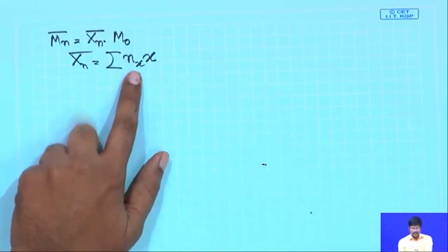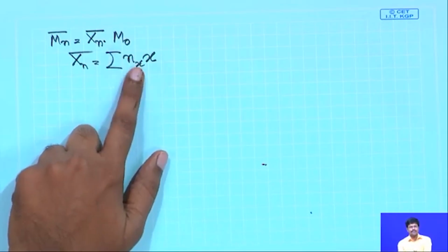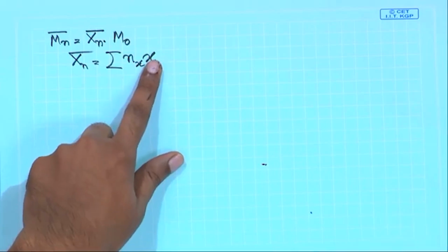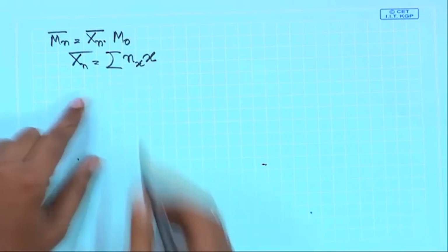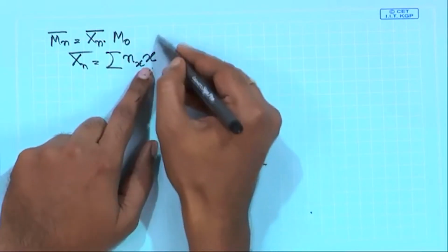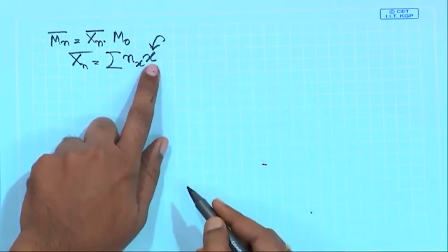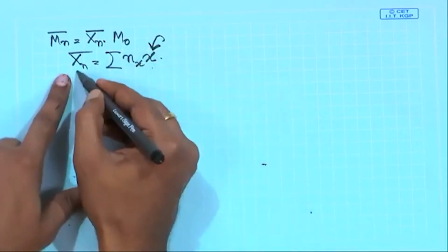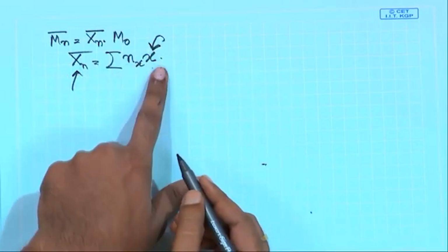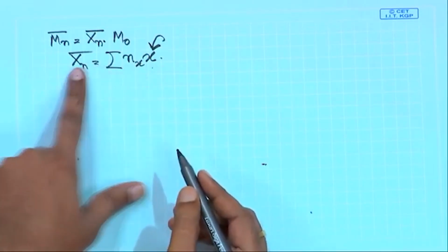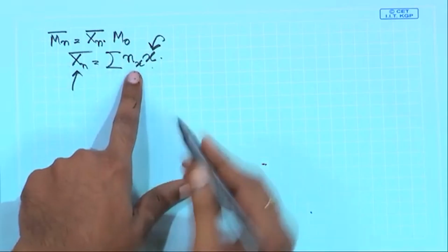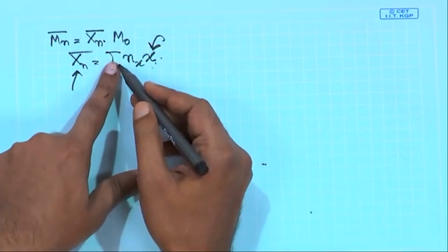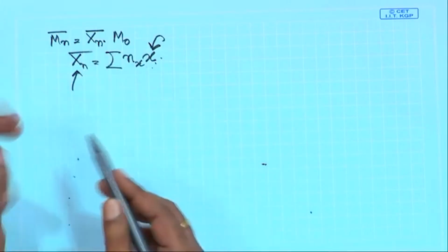This is the number fraction of x-mer, and this is the number of structural units. So, this x is your degree of polymerization, and this is the number average degree of polymerization. When you are averaging this, basically you are weighing this particular thing with a number fraction. So, this is also the concept of average.